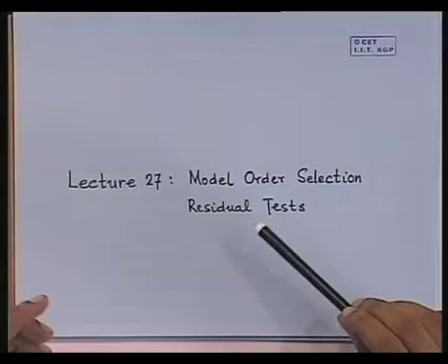In many cases, maybe you are trying to identify a nonlinear system using a linear model. In that case, there is no true linear model. There is no true parameter. It's only a question of approximating the nonlinear system behavior under a given kind of input.